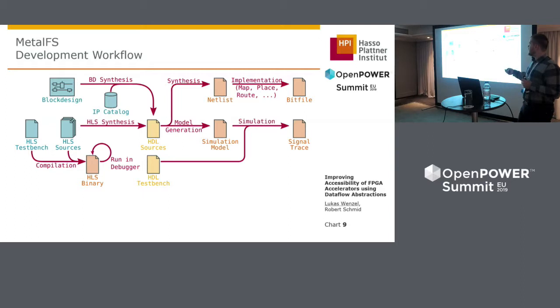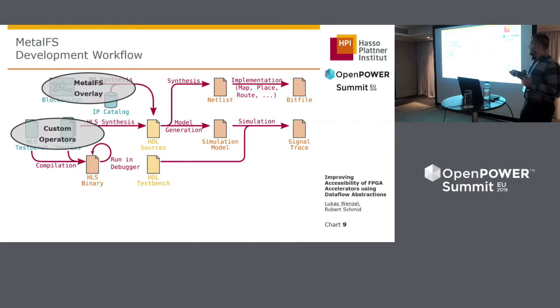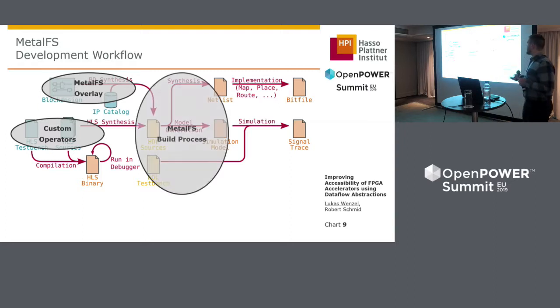And in this front end here, we have multiple ways Vivado presents us to work on a higher level of abstraction. Custom operators with MetalFS will usually be implemented in HLS because it's very fine to represent stream operations. The hardware side of MetalFS is implemented as a block design because that was the easiest way of defining that structure. And the rest of the demo you saw was this more integrated MetalFS build process, which handles all this part for us.